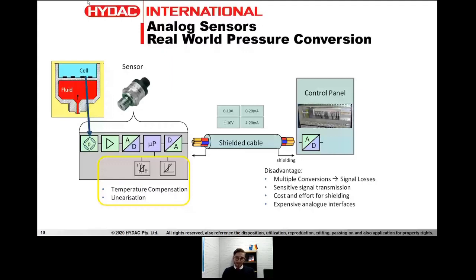And then that cable runs to a PLC, and in the PLC we have to convert it back again from an analog to a digital value, something that the microprocessor in the PLC can understand and read, and you can write logic based on it. The interesting thing is, if you had a sensor that only had a switch output, instead of doing a digital to analog conversion, you'd be doing a digital to switched output, which would be just an on-off instead of an analog value.